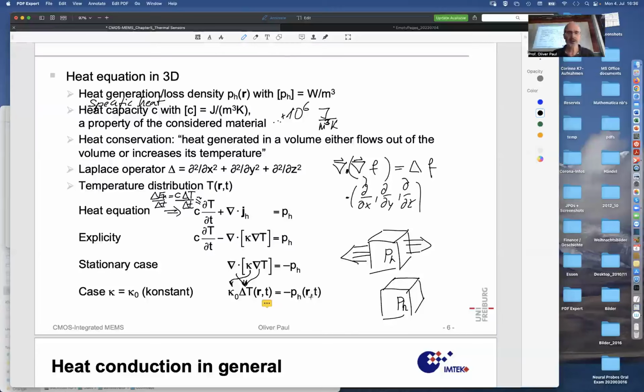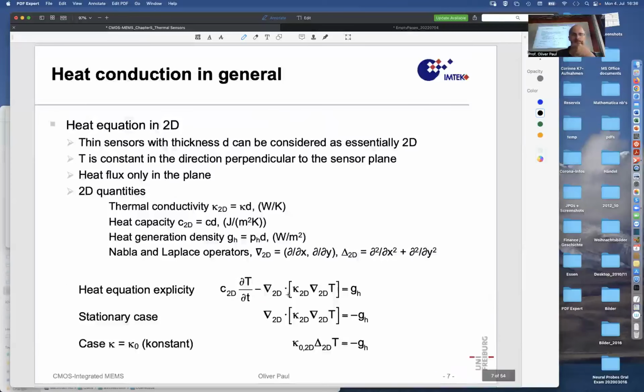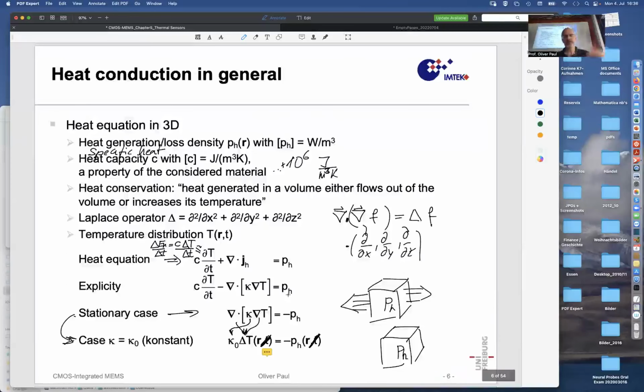And for that, standard solutions are available. Finite elements do that a lot. Let me just point out that we have to drop the explicit temperature time dependence here. It's no longer time dependent. It's stationary. So that is an equation that is worthwhile knowing. Very often, instead of having three-dimensional problems, we can simplify problems into one-dimensional form. And then everything becomes very simple.